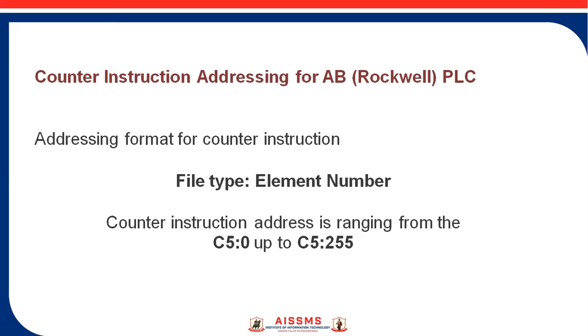So it is to be written as C5 colon 0 up to C5 colon 255, where 5 is the file type and 0 to 255 is the element number.